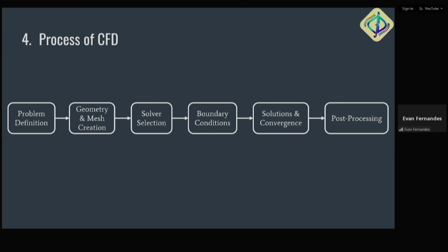If you want to find out some additional things from that simulation itself, like if I have an airfoil and I'm doing a simple flow over an airfoil, I've got my simulation result and it's computed and converged perfectly well. Then suppose I want to find out the Strouhal number of the frequency of the vortex shedding behind that airfoil. Accordingly, I can use those post processing utilities.